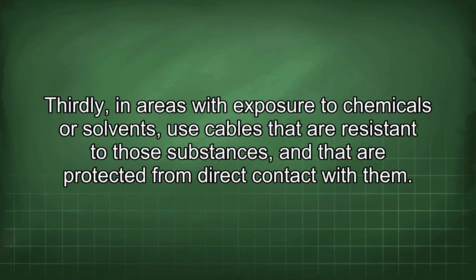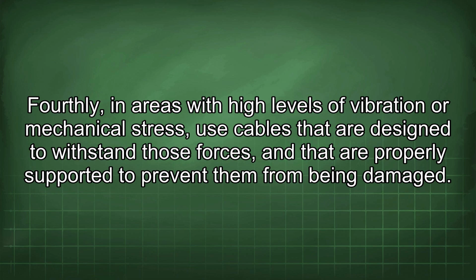Thirdly, in areas with exposure to chemicals or solvents, use cables that are resistant to those substances and that are protected from direct contact with them. Fourthly, in areas with high levels of vibration or mechanical stress, use cables that are designed to withstand those forces and that are properly supported to prevent them from being damaged.